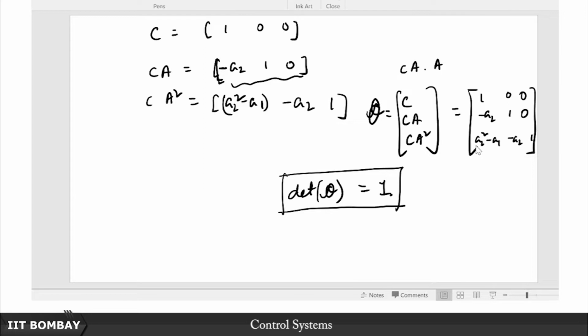So as I claimed in the previous day, I have now shown you, at least for the 3 by 3 case, and you can take this as an exercise to prove it for the general case, it is really not a big deal. I could have actually taken it just n by n here also, and a bit of mental gymnastics would have led you to conclude that indeed it is always going to be like this. So that is why this property of observability, as will be the property of controllability that we shall see next, these are all features of the way you are realizing the system.